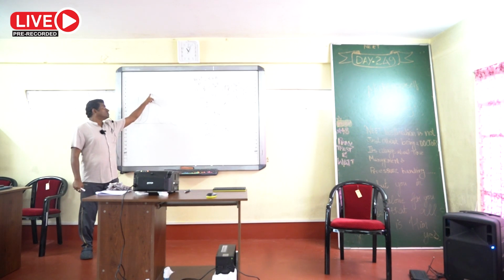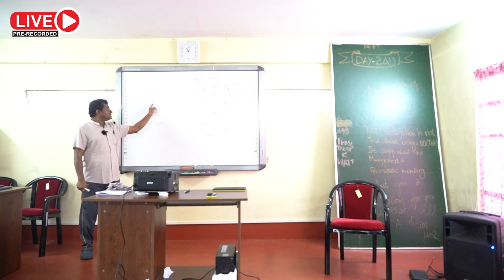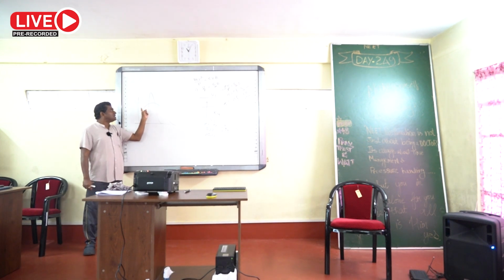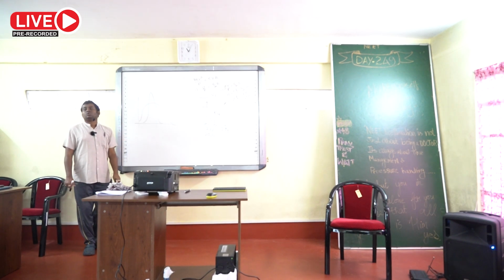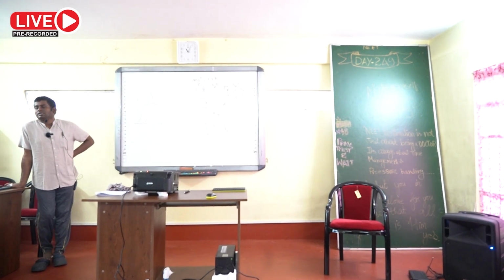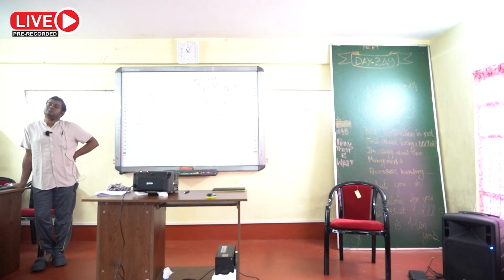Suppose you are going to listen to 98.3 FM. In the flat curve, 98.3, 96.2, 100 FM will all be at the same level. So for all, resonance will be flat, and all station sound will be overlapped. So this is a bad resonance curve. And this one is a sharply peaked resonance curve. So for the tuning purpose, we always require a sharply peaked resonance curve such that it can distinguish between the frequencies properly.